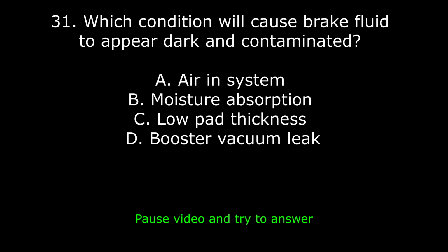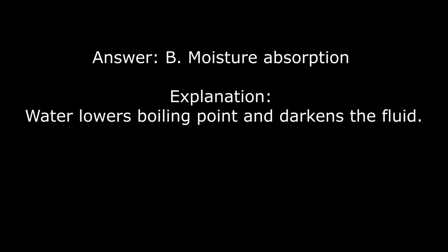31. Which condition will cause brake fluid to appear dark and contaminated? A. Air in system. B. Moisture absorption. C. Low pad thickness. D. Booster vacuum leak. Answer: B. Moisture absorption. Explanation: water lowers boiling point and darkens the fluid.